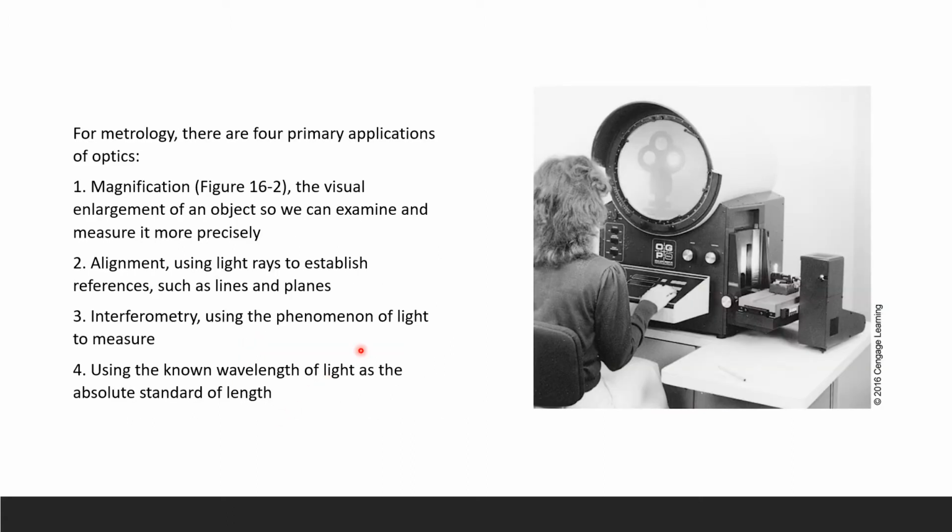In metrology, there are 4 primary applications of optics. The very first one is magnification, making it bigger: the visual enlargement of an object, so we can examine and measure it more precisely. Alignment: using light rays, we can establish references, and these references are nothing but, as we already know, lines and planes.